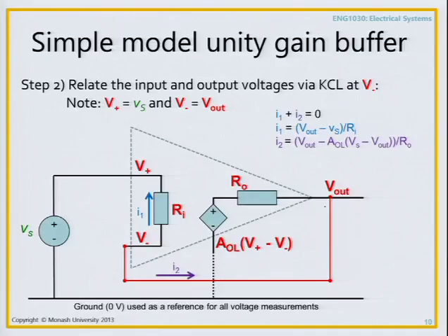Well, this red line all is really one node, right? So all the currents coming into or out of this node must sum to 0, and I've denoted those as I1 and I2. Okay, so we've got those here. And then we write equations for I1 and I2. So that's what we've got here. So I1 plus I2 must be equal to 0 because of Kirchhoff's current law.